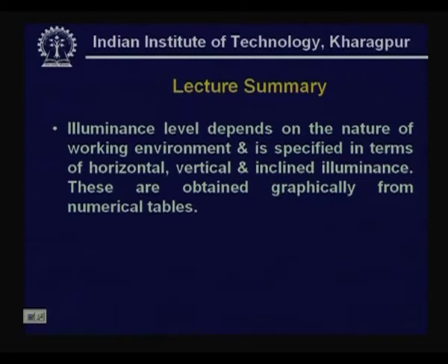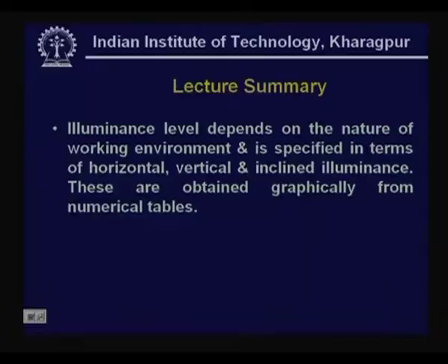Understanding that most of the sources could be either point sources or line sources or sheet sources. Remember, a point source has the illuminance varying as 1 over d square, where d is the distance to the point. A line source has variation as 1 over d, and a sheet source does not depend on the distance. This is the reason why in good large conference rooms, on the conference table,